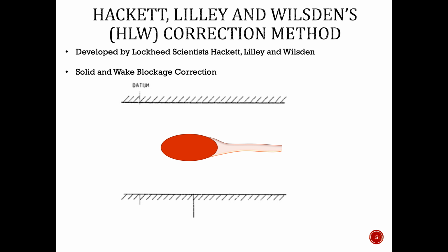When you place it, you know that the flow is going to accelerate around the curvature, not just because of the curvature, but also because you have this Venturi effect. As we talked about in class, that changes the coefficient measurements that you're taking from the tunnel.